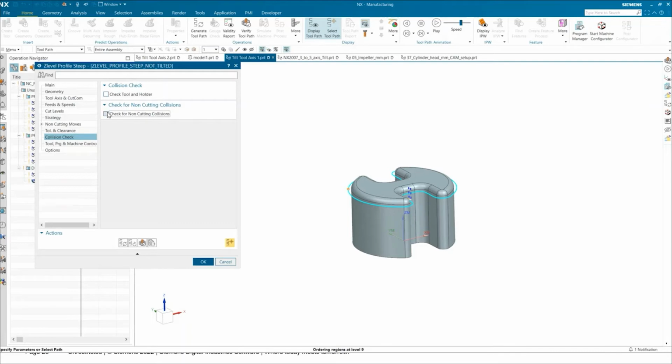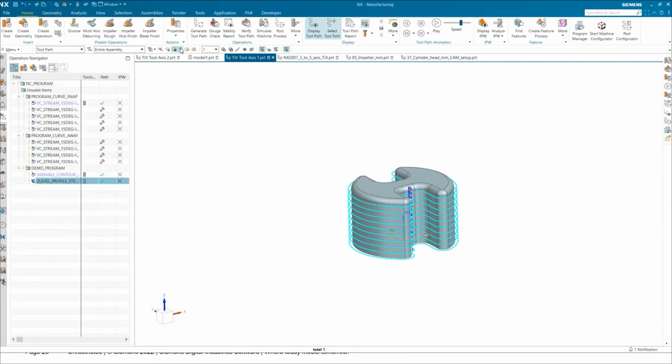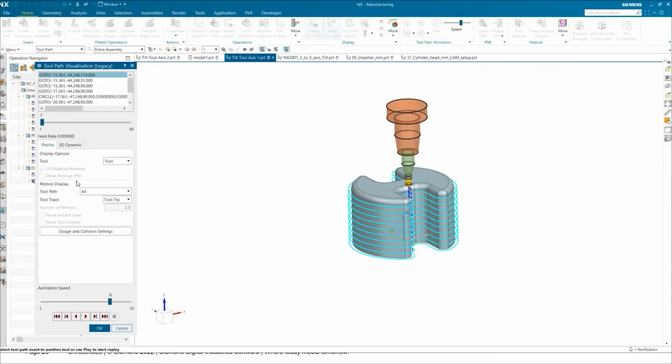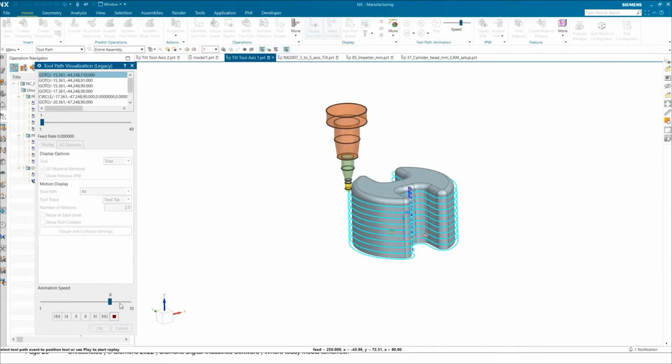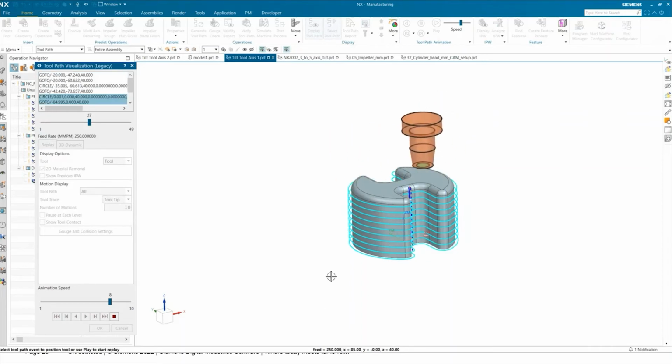Oh, I'm sorry, turn those off. If you have them turned on, they don't generate it. So there's my tool path. If I'm verifying that fairly quick, I can go down through here, and you'll see about the second, third pass, it starts colliding with the tool. So I will jump one ahead a little, but you can see I'm colliding with both the tool and the holder here.